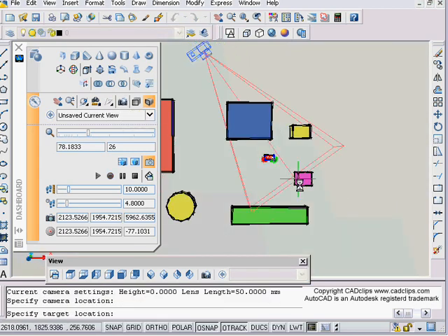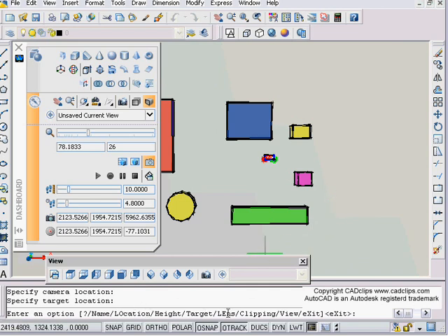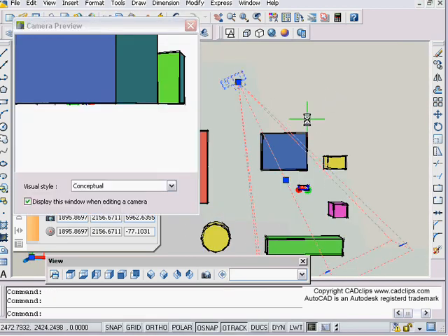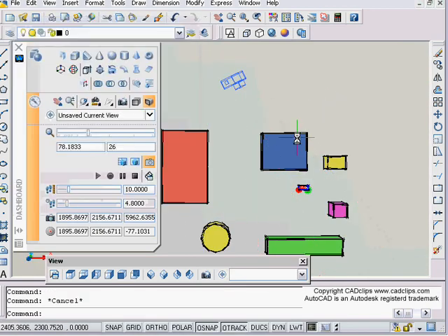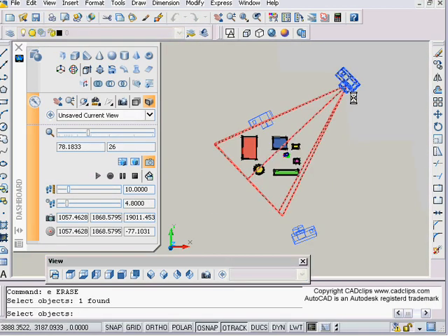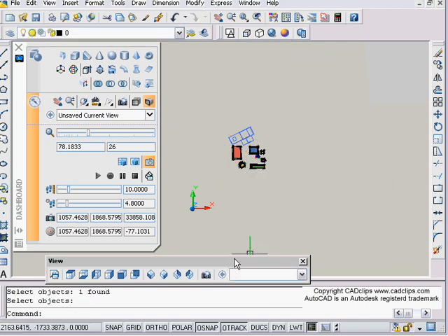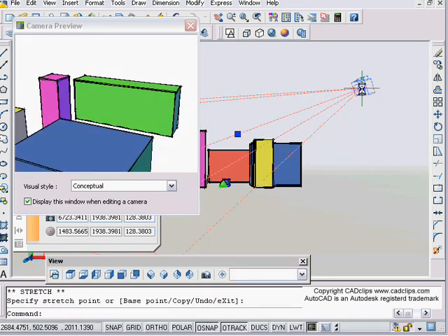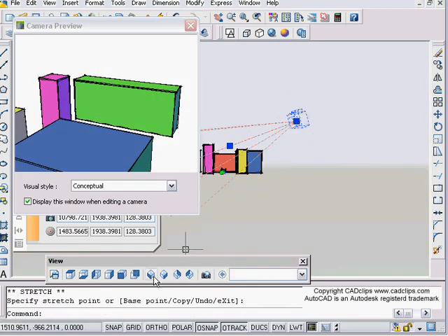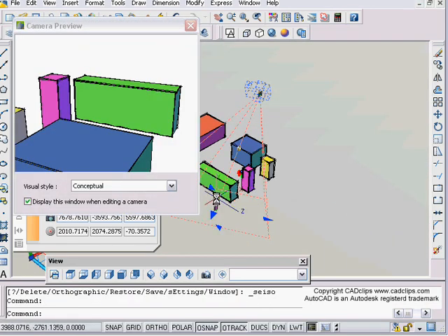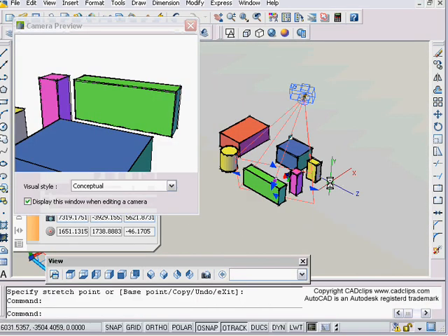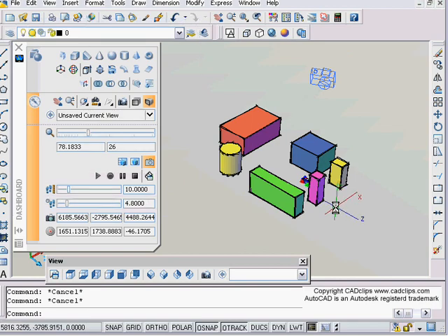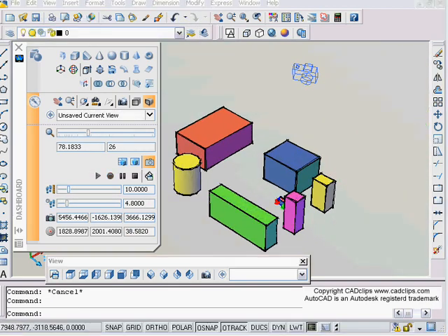Pretty straightforward. Pick the camera tool, pick a point, place it, and then have a look maybe at the help menu and set some more options. Basically, I just place it, and then after you set, notice your Z, change your Zs, etc. You could also go in here and move the camera just by going into, for instance, let's go to my right hand side view, okay, and I can grab that camera, and I can also move that camera up just by doing that, going into that view. Okay, going back to my 3D view, click in here, so off you go. So put your cameras in and then rename the views, and then take those views and put them in paper space and plot them out.